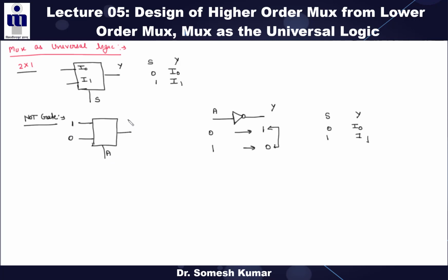So we can write the expression for this now. This is a 2:1 mux. You know the expression for this 2:1 mux. This is your select line. So A bar into 1, next we can write A into 0. And this Y is here basically A bar. Now does it behave as the NOT gate or not? Yes, it behaves as the NOT gate now.